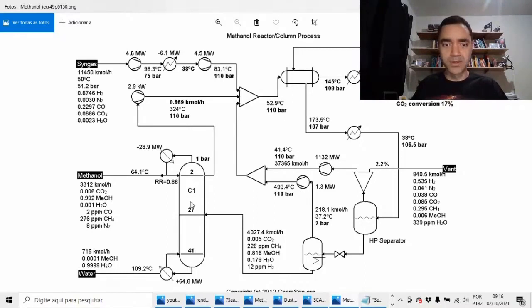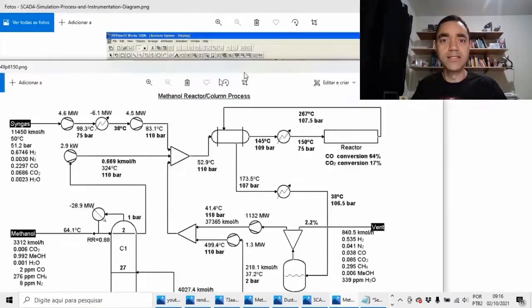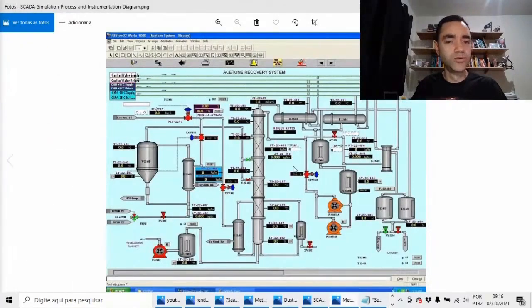So these components must be shown in the control room. And the more organized your process flow diagram is, the easier it will be for the automation team to use that as a reference and build the human machine interface in the SCADA or in the screens used to do the operations and the control.